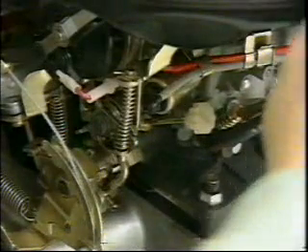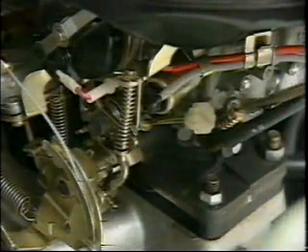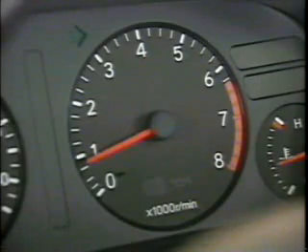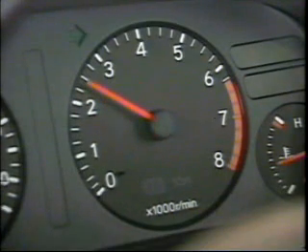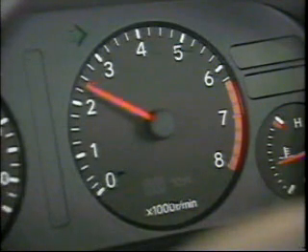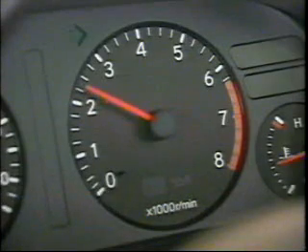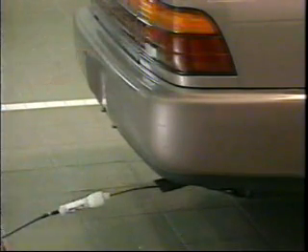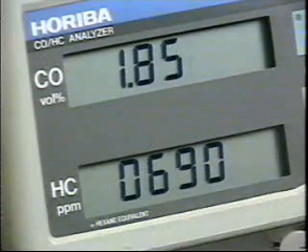Repeat these two steps until the engine RPM will no longer go above the highest permissible idle setting. Finally, turn the idle speed adjusting screw to set the idle speed to the specified setting. After this, rev the engine to about 2,000 RPMs for 30 to 60 seconds. Give the idle speed 1 to 3 minutes to stabilize, then test the exhaust by inserting the CO meter probe 3 centimeters or about 1.6 inches into the tailpipe.